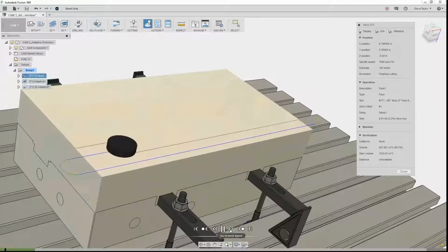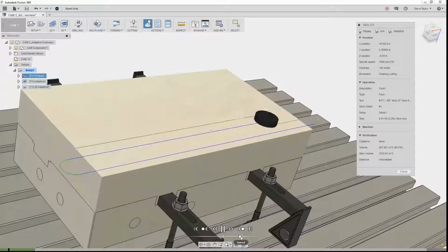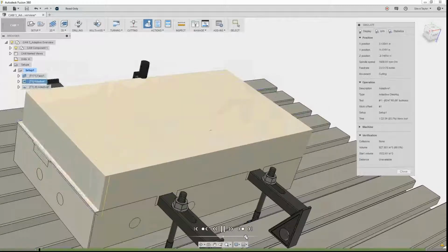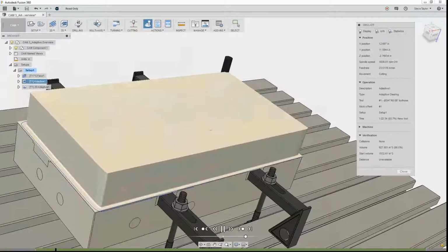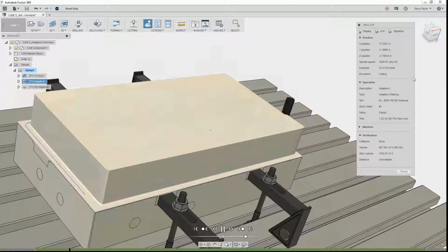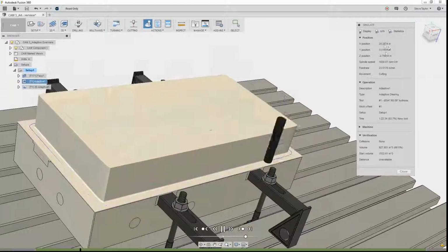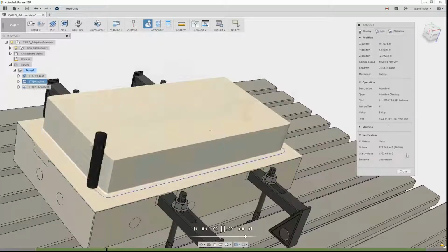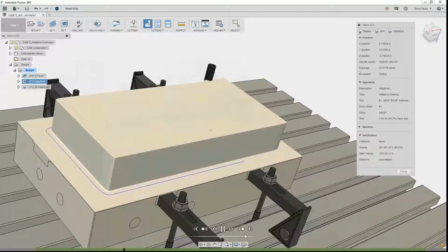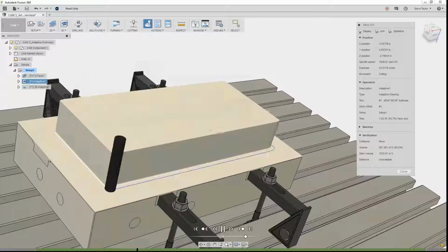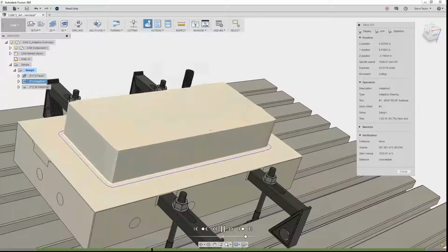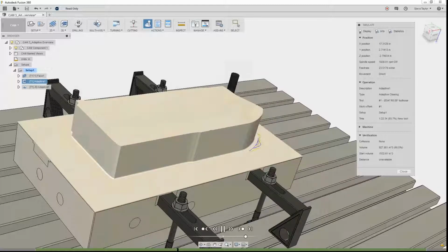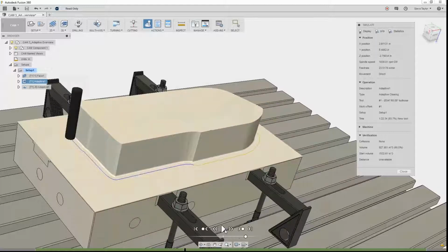I've got some controls. I can move to the next move. I can speed, so I can increase the speed of the cutter as it moves along. You can see how the information, the position is changing in this information up here, what setup we're on. So it's faced the top, then it's doing our 3D adaptive clearing. You can see the depth of the tool in the material. We can pause the operation if we want to do.